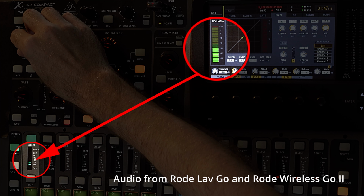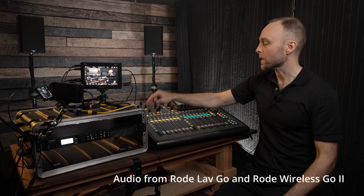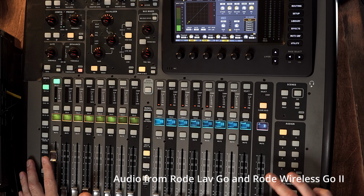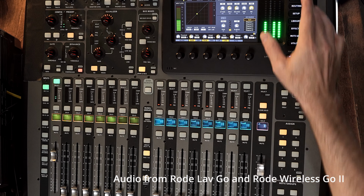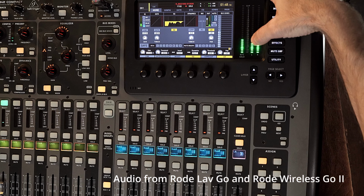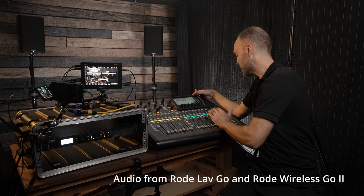Check 1, 2. I'll go ahead and give it just a touch more. Even if I get loud, I'm not clipping out the preamp, so that's a good level. Now I'm going to leave the main fader down. I'm going to push my channel fader up to unity. I'll push my main fader up to unity. Check 1, 2. Now we can see here on both the input and the master output, I've got nice, strong, healthy levels. We'll go ahead and set those.